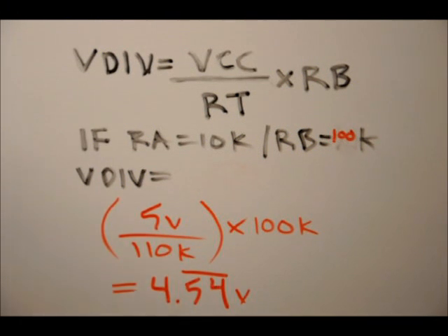So if you round up, 4.55 volts. So it could be more or less depending on how dark the environment is. In the case of light, if there's a lot of light hitting the sensor, it could be about 1 kilohm. So we're just trying to get a basic understanding of how we're going to be using our voltage divider for our secondary laser tripwire circuit / light sensor circuit.